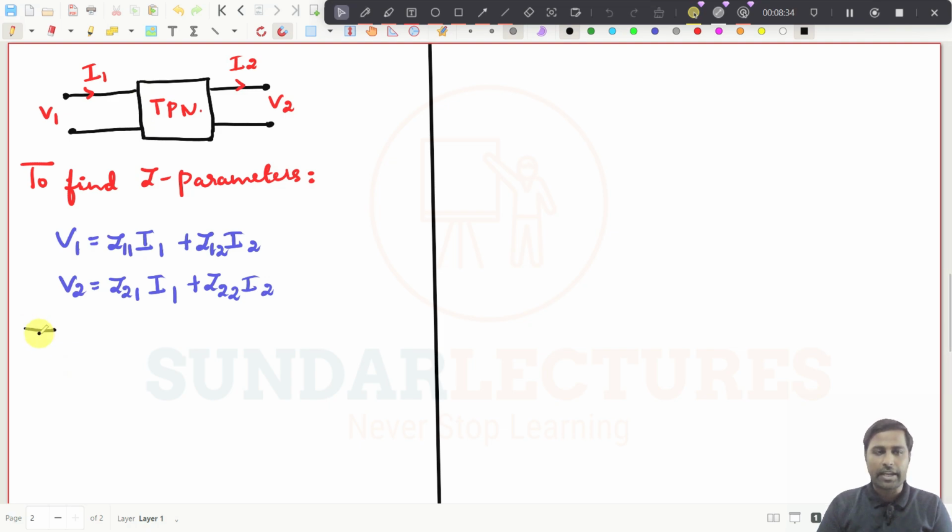First, to find Z11 and Z21, what you have to do? You just open circuit the secondary, the output port, and you excite the input port.